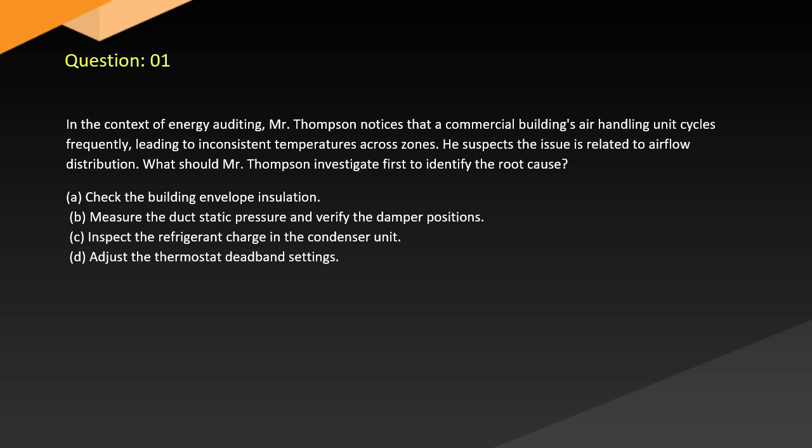A. Check the building envelope insulation. B. Measure the duct static pressure and verify the damper positions. C. Inspect the refrigerant charge in the condenser unit. D. Adjust the thermostat deadband settings.